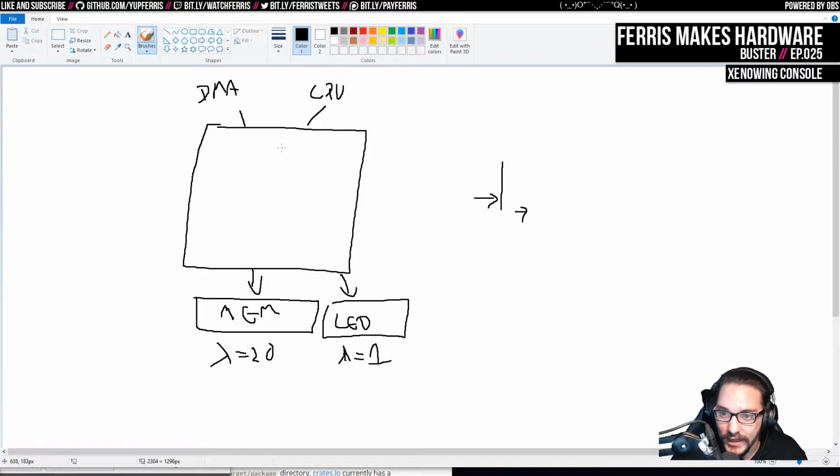But then I want to have this read return FIFO, which I'll actually draw here. So let's say this had 0 and then 1. And then also the data coming back from here, I'm going to stuff into individual FIFOs. So there's one here, and there's one here. And so let's say this came back with B, and this one came back with A later. It wouldn't really matter, because what's going to happen here is that then something's going to pull this off into a little buffer. And so this is going to say 0. Cross that out. And then it's just going to sit there idling until it gets something back from 0, right?